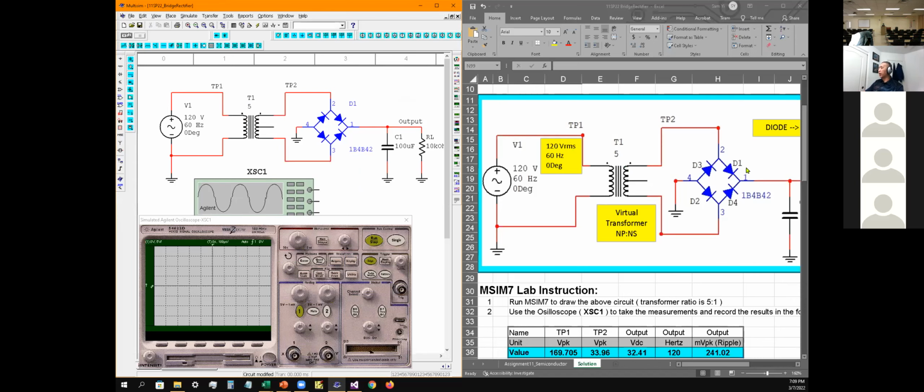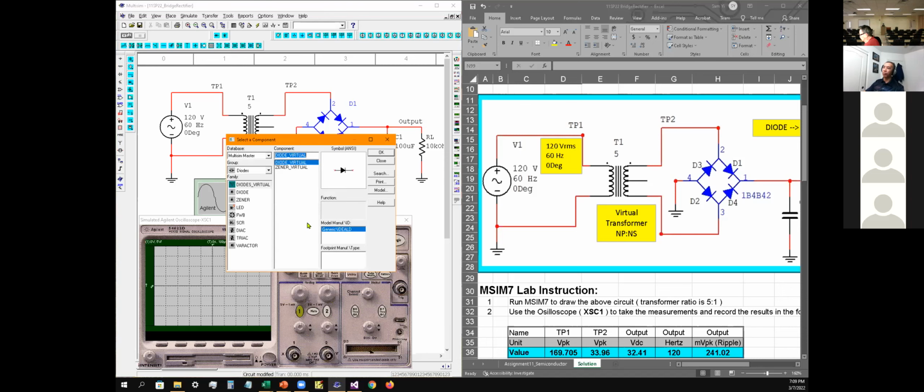And the other one that we need is this bridge. So what you want to do is go to your selection. It's in your diode. It should be on the very side here. The third one, which is the diode, you can see it on there. When I put my cursor on it, it's a diode. I click on that, and then I bring up this here. Okay, they give you the selection menu. And then this one is going to be your diode.